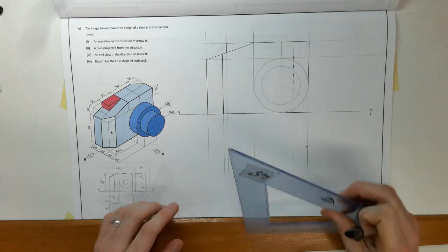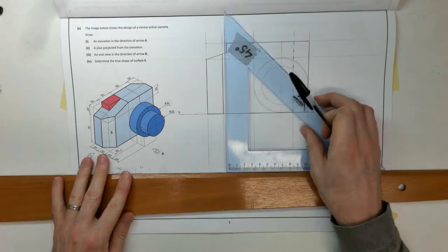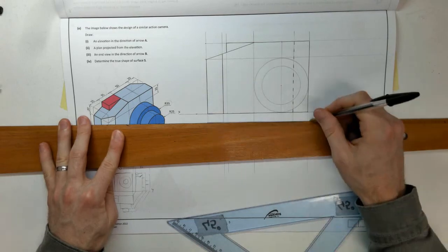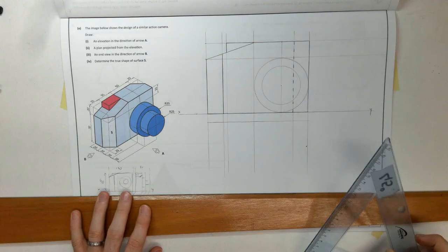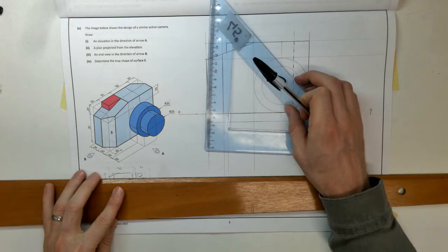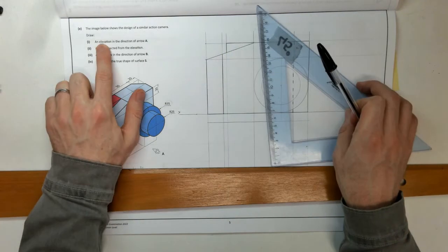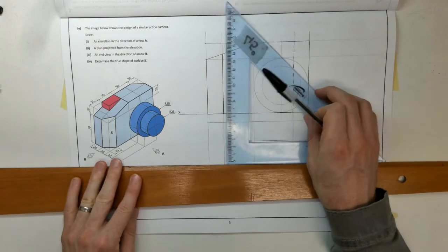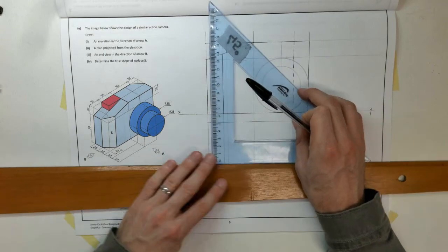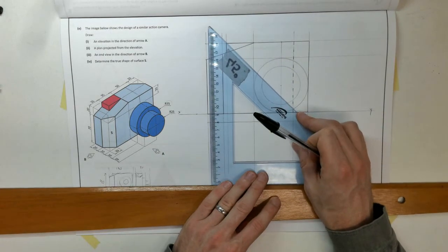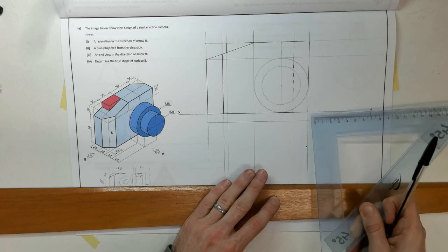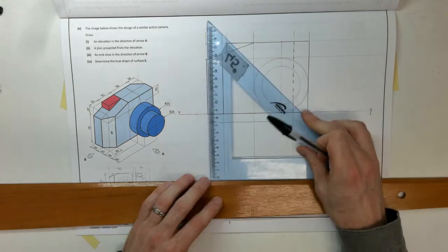Now let's come down, like I said, leave a little gap of about 10 or 15 mil. I'm not even going to measure it. I'll just draw my light line there for the back. Okay, and I'll measure off my overall depth of my object. So going in order, I have elevation done, now I'm on to plan. So we've got 20, 20, 20, 20. Let's measure off all of those. Should just about fit on the page here.